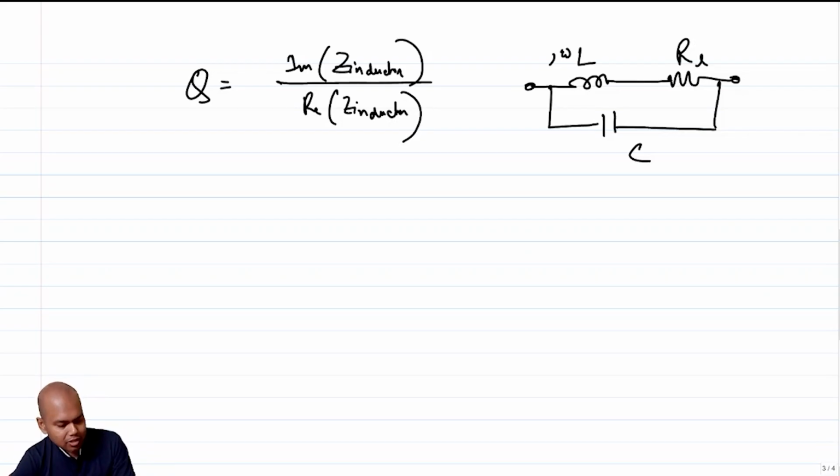Now, what is a capacitor? It's probably one of the simplest electrical elements that you can get. You have two metal plates. You put them very close by, which means that you have electric fields which will be confined between the two plates, and you get a capacitor. The closer the plates, the higher the capacitance. And fortunately, in IC design, you can get metal plates to be very close to each other, simply because we are talking about extremely small geometries, right?